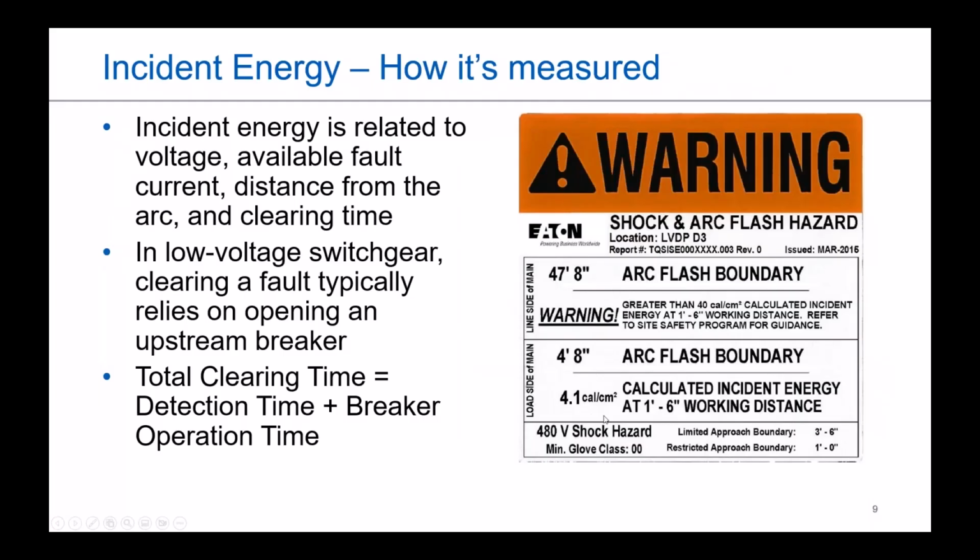You'll have one when you are protected by the arc quenching system, and you'll have one when you're not. So if you didn't have that spare on hand, you would basically have whatever that unrestricted incident energy level is, which will be fairly high. So that's just one thing to keep in mind: if you didn't have the spare, you could still be up and operational. You just won't necessarily have the protection on it.